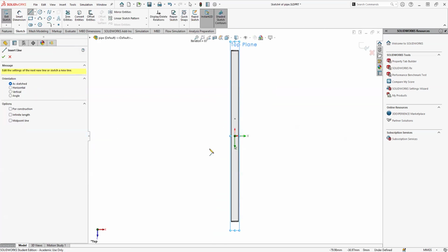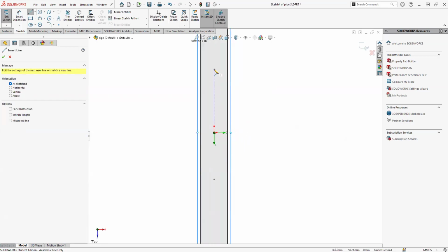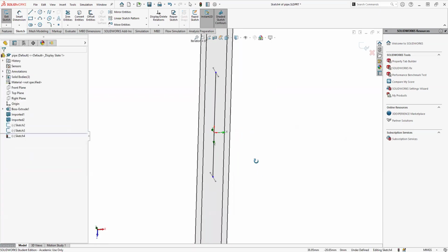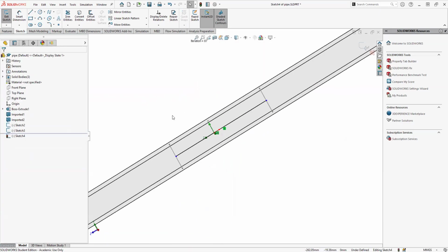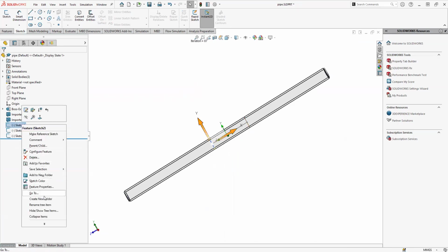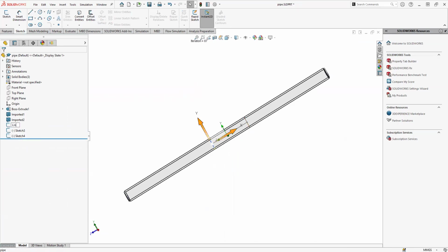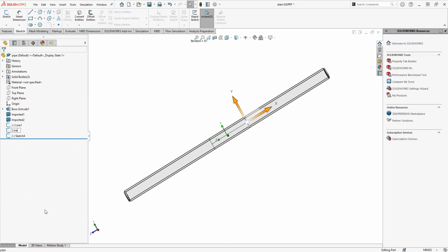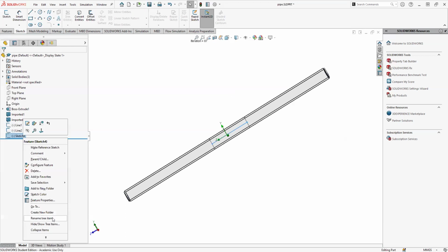And then based on these two points, I could select a line on top of them. And now you can see how I generated the lines. If you look into these lines, there is no relationship between them. Name them line 1. It's just random lines. I select them because I want to see the velocity profile along these lines. Line 2, and the last one, line 3.